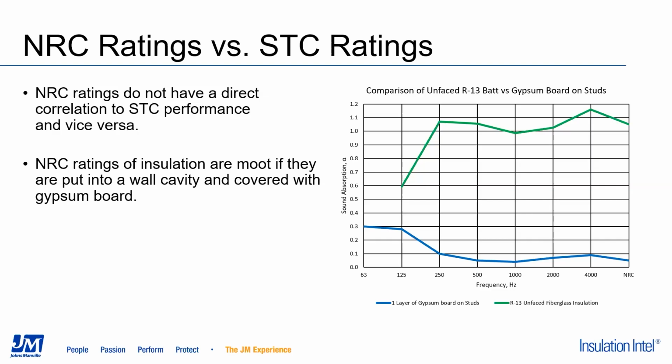So on the right, we see this figure where we have an unfaced fiberglass product being exposed, and we did a C423 test on that. And that was just laid on the floor, nothing on top of that. So we get really good absorption with that product. But once we stick that behind a wall and we have a gypsum board covering that material, you have the same performance that you would see with just a gypsum board or on par. So you're getting a lot more reflectivity as a result of covering it with gypsum board.